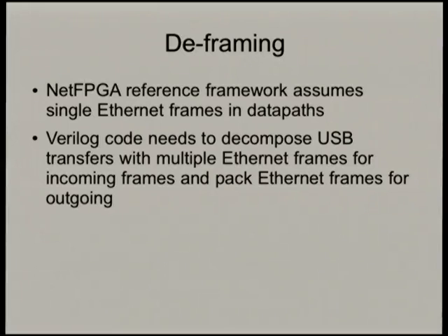So the Verilog code needs to be able to read through the chains of headers and take each Ethernet frame out and present them to the NetFPGA switch reference design one by one. And similarly, when there's frames coming through that need to go back, we need to repacketize those, and there's a bit of timing involved there to know just how many to repacketize. So there's a bit of work to be done there yet.